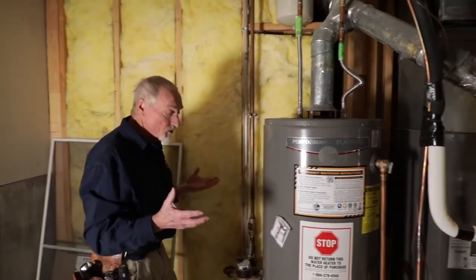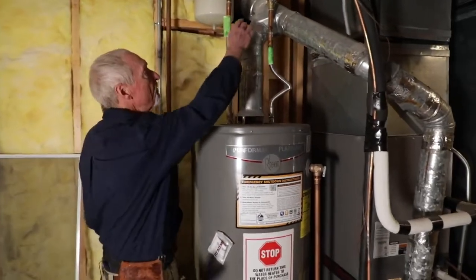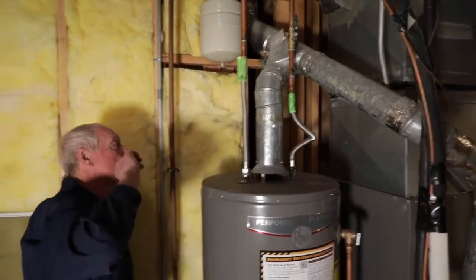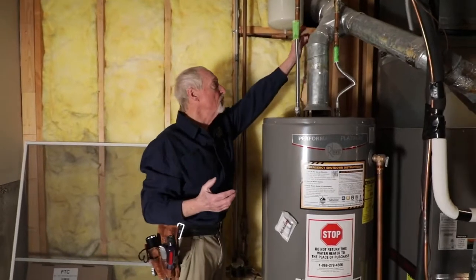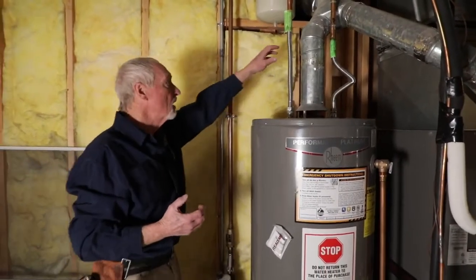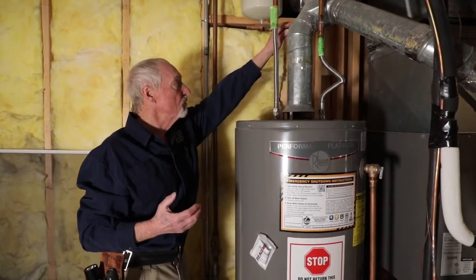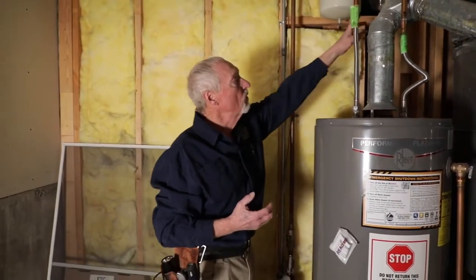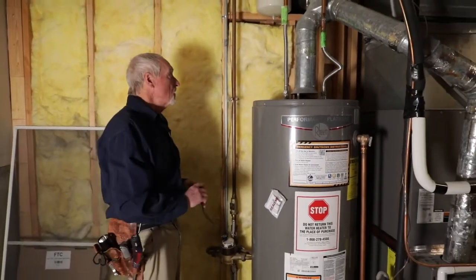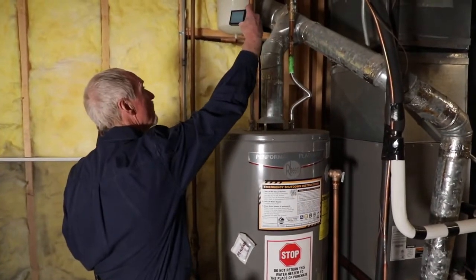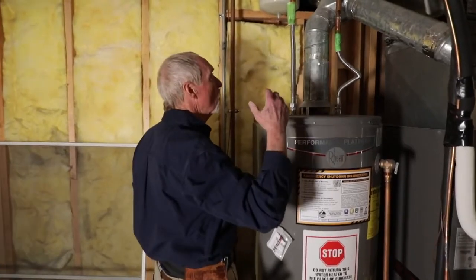So while we're all standing here with our water heater, we see right out of the gate we have foil tape up here on the flue, and once again, foil tape not allowed in most areas. It hides the quality of the connection, and it's not approved for use most of the time, and so we would call that out as a defect. So I would take my camera and take a photo of that. Even if it's a minor defect, it's still something we want to point out.